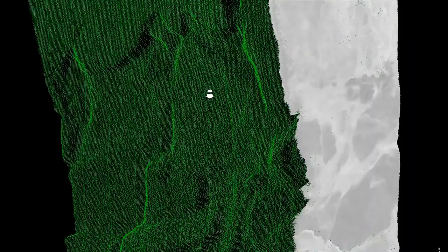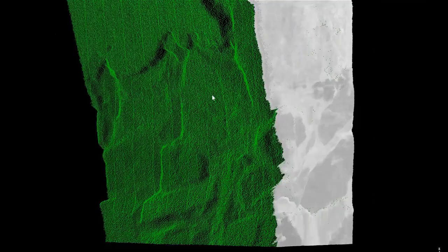Now, if we look a little bit closer at the details between the two different scanners, if I zoom in on the data from the TX8, you'll see I'm zooming in at the black writing on this sign. You can see a lot of detail in that. If I zoom in on a similar area with the SX10, you start to get spaces between the points very quickly.